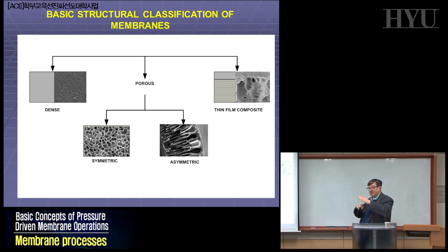In some cases, the different mechanisms interact or overlap a little bit, making life more complicated. But you can go from the dense membranes with no pore at all to the very porous membranes. The membranes can also be symmetric or asymmetric. And that's very important because you will learn that mass transfer across our membranes is very much related to the thickness of the membrane itself.